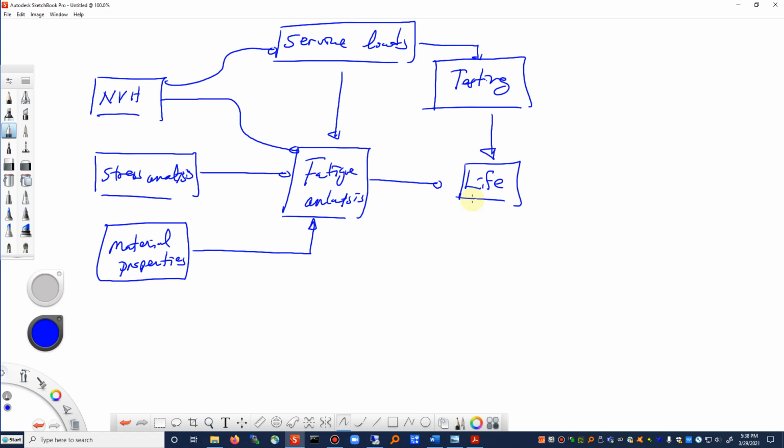In kind of the middle phase of this process, you might have finite element analysis for durability, design iterations to save mass and so forth, the mule testing, prototype testing, updated loads and life targets may come about. And kind of in the later stages, you may get some sort of component, subsystem, or full vehicle tests. And then there's often last-minute fixes that have to take place.